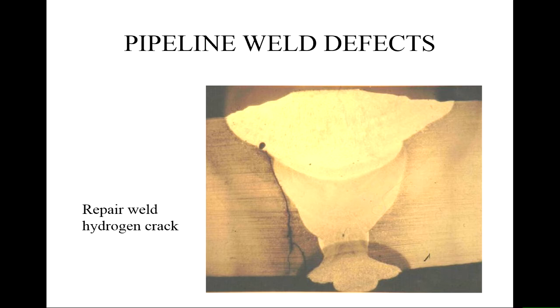And in one pass, it's very likely to introduce high stresses in the heat affected zone, and the heat affected zone will contain hard and brittle phases. So that's why nowadays most of these repairs that are carried out for the root bead involve at least two passes. The role of the second pass is to produce a little bit of tempering in the heat affected zone created by the first pass.